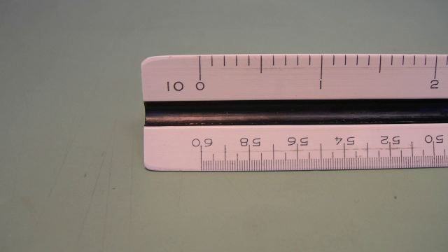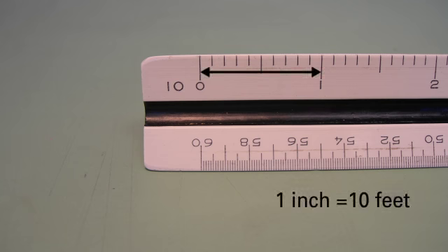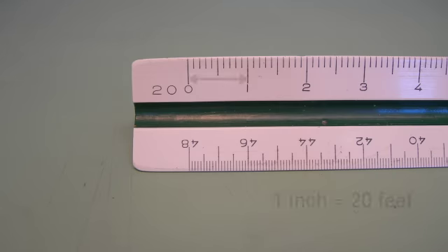Each of these graduations refer to the number of divisions that are marked on the scale for each inch. These scales have the meaning that 1 inch is equal to 10 feet for the 10 scale and that 1 inch is equal to 20 feet for the 20 scale, and so on. Each mark is then taken to be 1 foot.